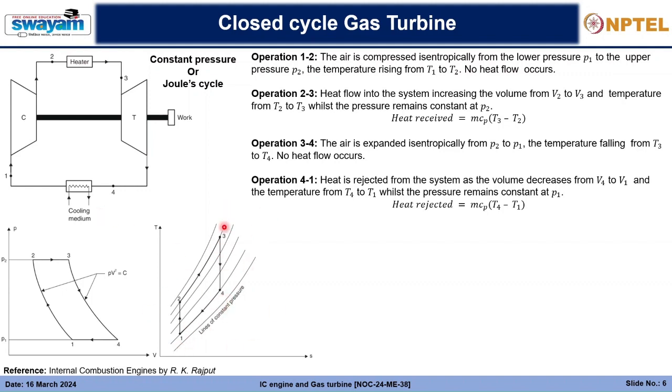Similarly, there are constant pressure lines, and this can be isentropic, since these processes can be isentropic when a more controlled environment is possible. But even if these are irreversible adiabatic processes, we can also solve for that. We know how to solve for that. We'll only have to utilize the efficiencies associated with the compressor and turbine. So that doesn't matter.